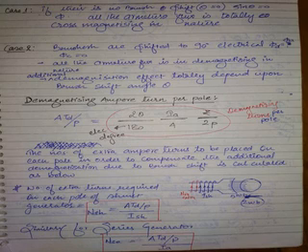So how is the armature flux now? If the brushes are here, the armature flux is like this. If this is the armature flux and this is the main flux, both are directly opposing, demagnetizing. If phi a is like this, it will only cross magnetize the main flux. If phi a is like this, it will only demagnetize the main flux. If phi a is like this, it will do both. The two things depend on theta. As theta increases, demagnetizing will increase. Sin theta, theta proportional. So as theta decreases, demagnetization decreases.